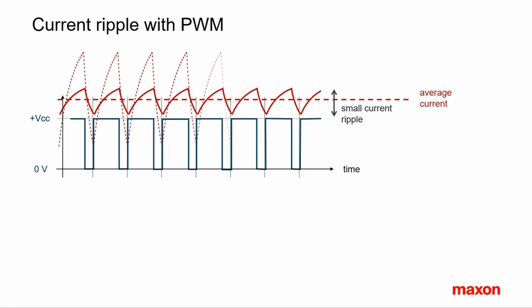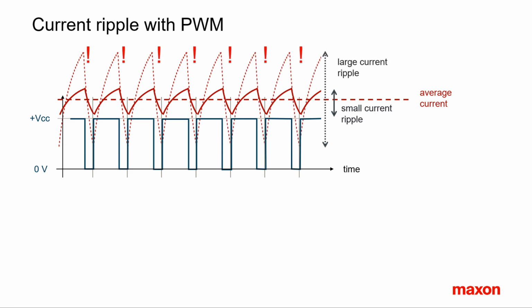A large current ripple can lead to excessive motor heating, because the ripple peaks will heat up the motor more than proportionally. Hence, there is a strong interest in reducing the current ripple, and this is the main focus of this tutorial. The maximum torque ripple can be approximated with this formula. The formula is easy to understand, and hence the measures to be taken for reducing the amplitude of the ripple as well.